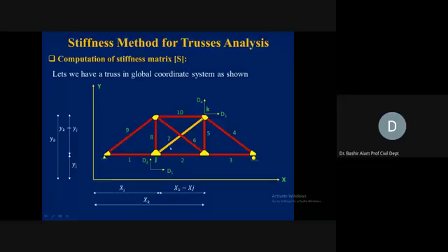And joint J of this member 7 is located at xj. And the far end, which is joint K, is located at xk. X, which one x? We are taking this in the global axis system now. So the horizontal projection of this member 7 is becoming xk minus xj, which is written here. This is the horizontal projection of this diagonal member 7.